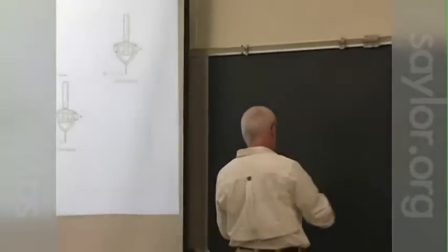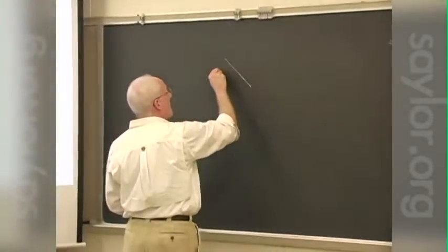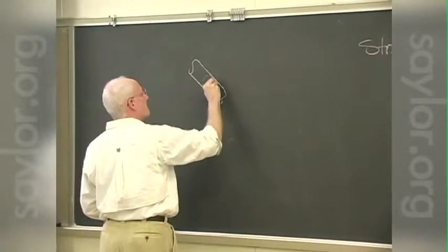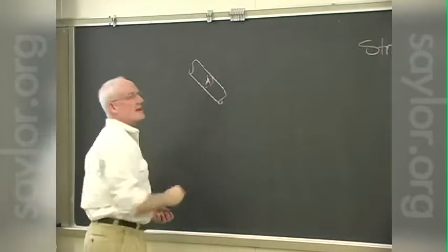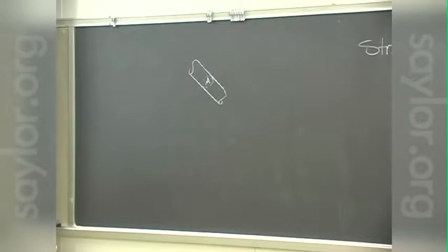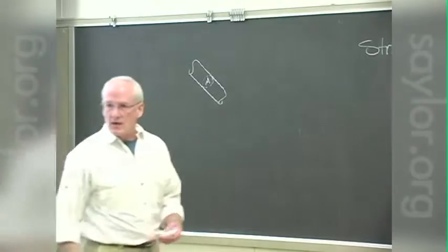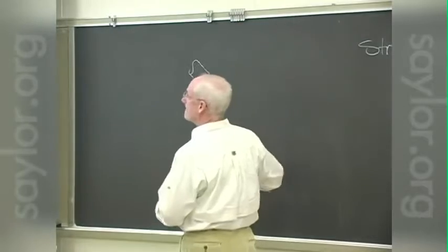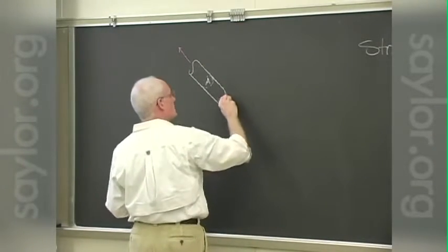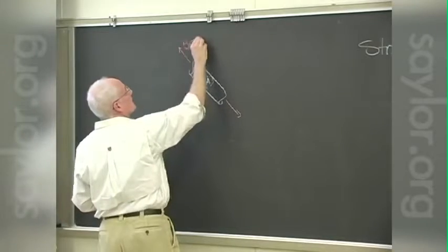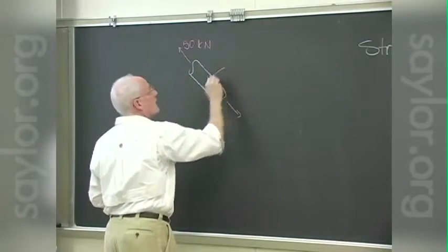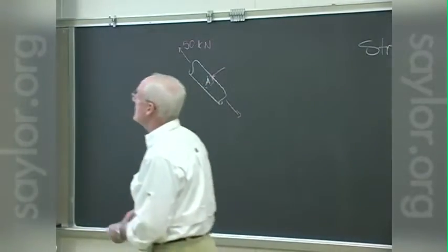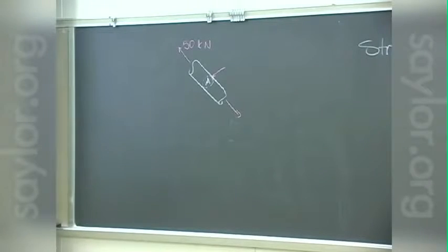Now, in the center of the piece, we have this cross-sectional area, the little exposed part there, for example. We have that cross-sectional area that needs to withstand the forces on there. And if I remember, that was 50 kilonewtons, was it not? And that cross-sectional area itself is, well, the piece has a diameter, you notice, of about 20 millimeters.